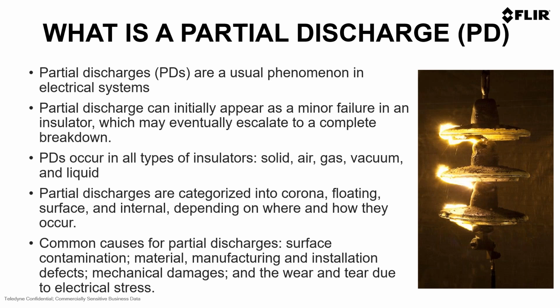So common causes for these partial discharges are, for example, surface contamination, and that can be the conditions of the environment: humidity, dust. But it can also be material manufacturing and installation defects. So in case that while manufacturing one of the components, it was contaminated, for example, or it didn't.